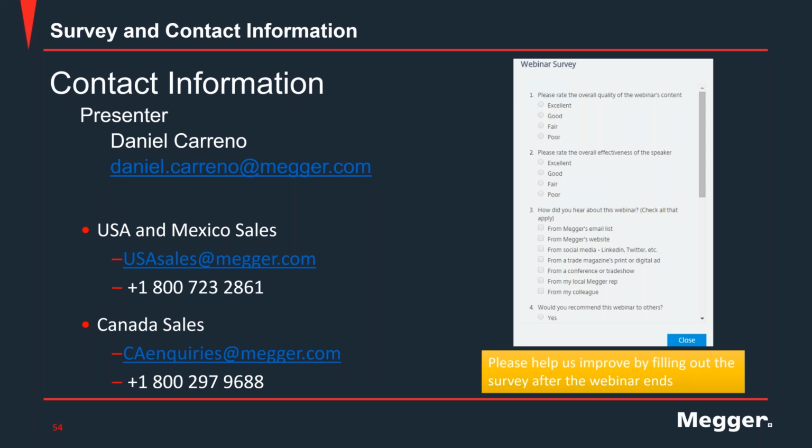At the factory, I should also add that it's done as acceptance testing. Besides that, in-process testing is also carried out by manufacturers of bigger power transformers, where this test is carried out at different stages during the manufacturing. This test holds a lot of value because it is done not only after the transformer is manufactured, but also during the manufacturing process.